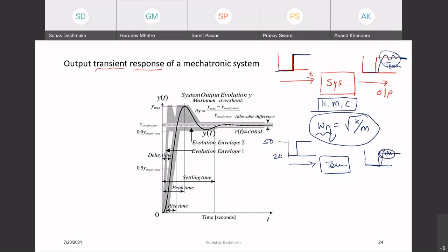This phase is called the transient phase. This phase is very important, and for any sensor, this transient should be very minimal. This time should be in microseconds or milliseconds. If it is more, your system may not result in accurate measurement.